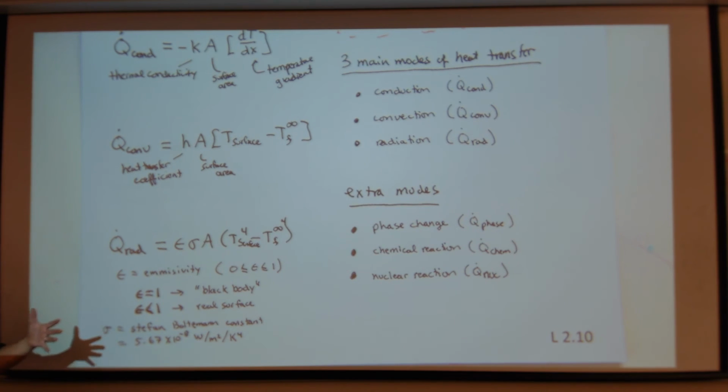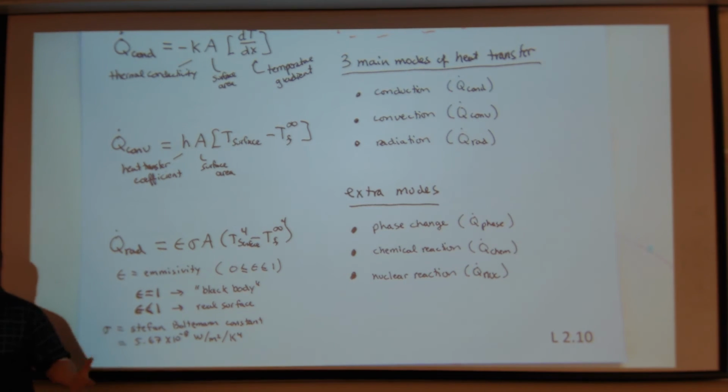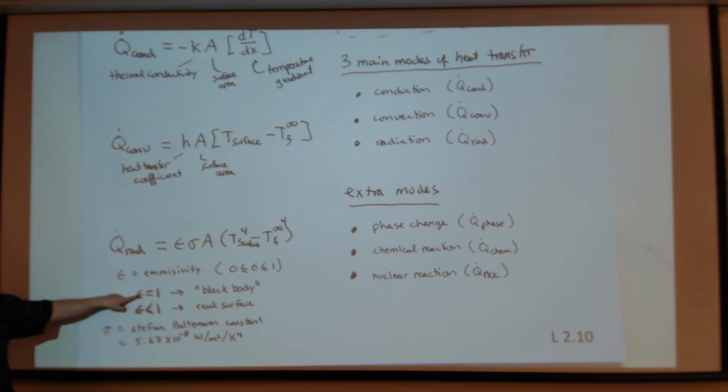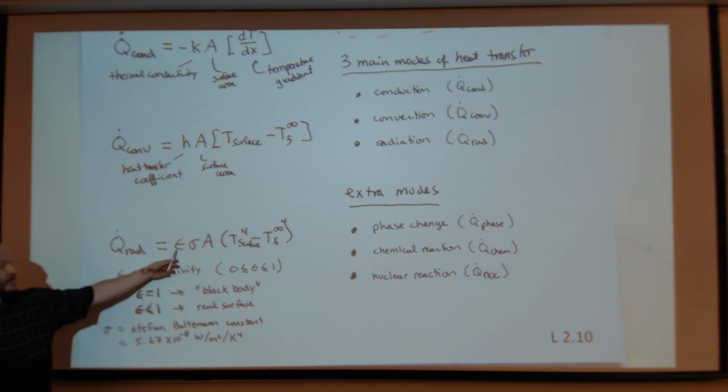If I were to take a shiny, say silver, wood-burning stove, given it's silver, its emissivity is going to be on the order of 0.2. But if I want that stove to heat my room better, I need to increase its emissivity. So they just spray black paint on it, which increases the emissivity at the surface, and you get a larger heat transfer.